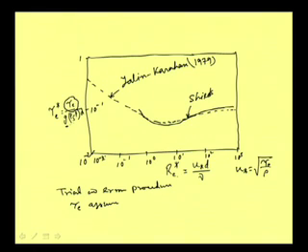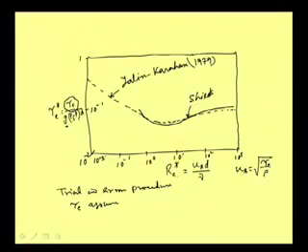For those situations several experiments have been done, and some investigators have given the value of tau c, critical shear stress, as a direct expression relating to g rho S d. Some empirical direct relations are also there, and these are also empirical, but they are more extensively done with a lot of data, so the tau c calculated by this will be more accurate. Of course, assumption is always there in all these analyses.